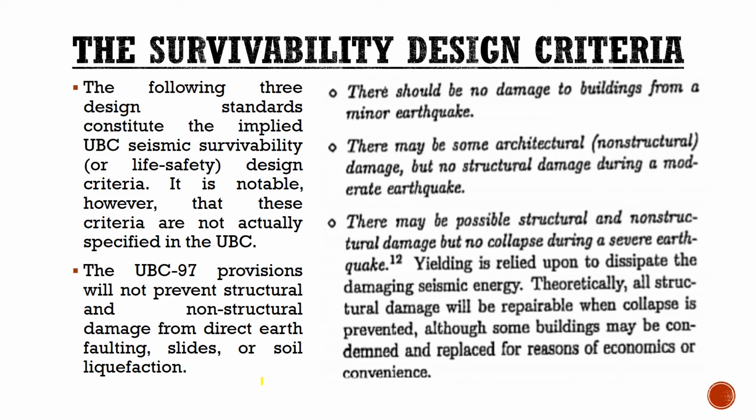Okay, the following three design standards constitute the implied UBC seismic survivability or life safety design criteria. It is notable, however, that these criteria are not actually specified in UBC, though they are derived from these design standards. Okay, so the UBC provisions will not prevent structural and non-structural damage from direct earth faulting, slides, or soil liquefaction.